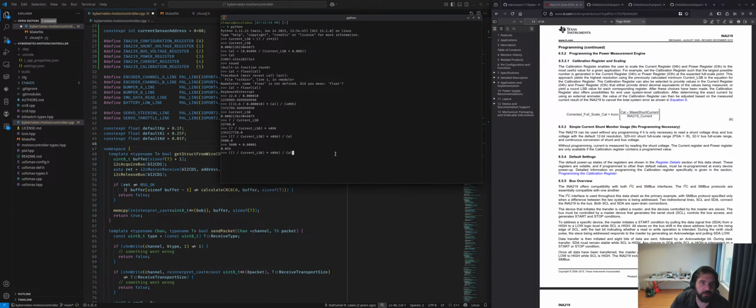So we could probably, if we're here, hold on, ohms times 0.001. How many amps can we measure with the 40 millivolt range? If we did 0.4, okay, so 5 amps. With the resistor that I chose, we can measure 5 amps, so 25 watts essentially.